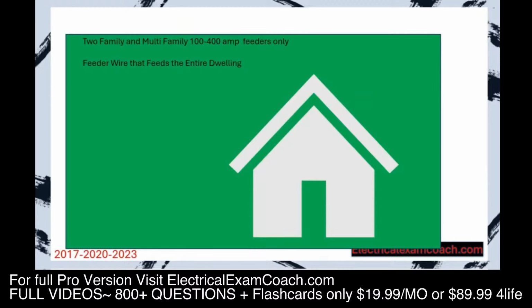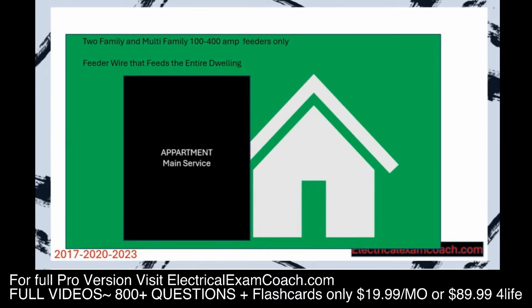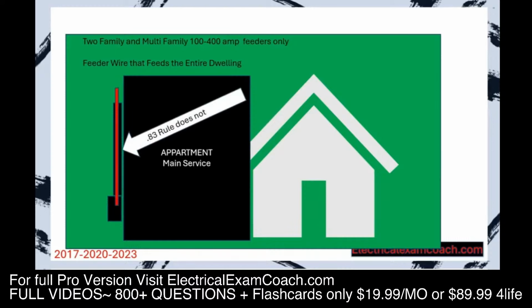Let's dive into two-family and multifamily. This is 1 through 400 amps, and this applies to the feeders only. The feeder must feed the entire dwelling. Let's imagine that you have an apartment here on the right-hand side, and it's attached to the larger apartment structure. That's where the main service is. Let's imagine that you have your meter center out here, you have your service riser, and then you have your wire going up. That wire there, the 83% rule does not apply.